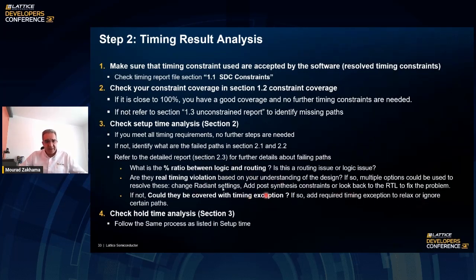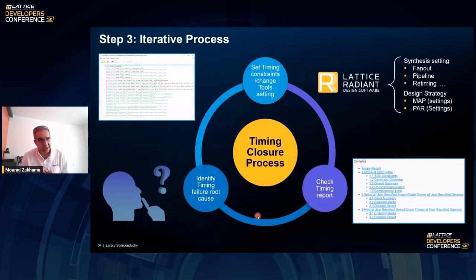So that's kind of step 3. It's very unlikely that you have a hold time violation, but in some cases you may, and you need to do the same steps with the hold time analysis also, which is section 3 of the report. So I think following this process, you should be able to get a good methodology for resolving any timing issue.